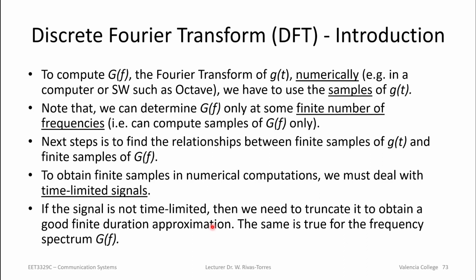So that was the end of the power spectral density. Let's talk about this concept of a discrete Fourier transform. Even if we go back to lecture two, when we started talking about vectors and creating a signal as a vector, we were doing discrete samples. We were looking at the signal and picking those samples that we wanted at certain time intervals that we call the sampling time. We can actually do the same thing with the frequency domain.